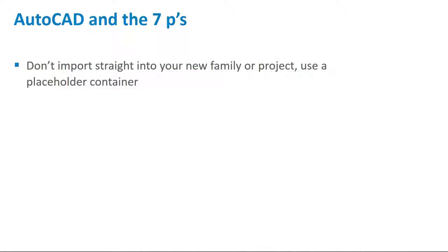So, as I said, don't import straight into your new family or project. Use a placeholder container. So, if you start a blank project, you can bring your DWG in there, explode it, and then cut and paste it all out into your real live project.